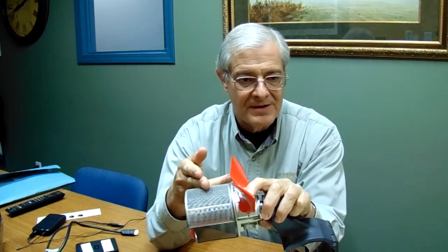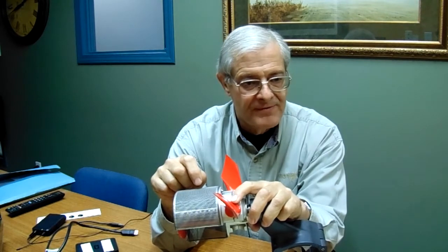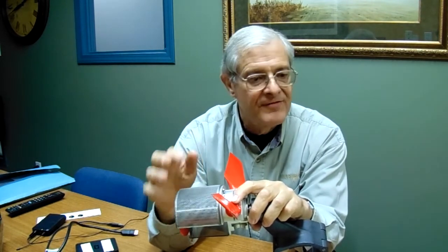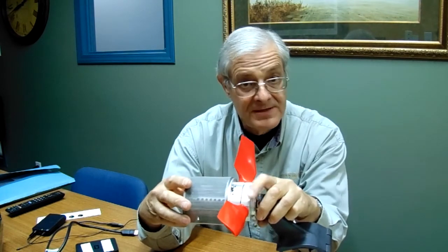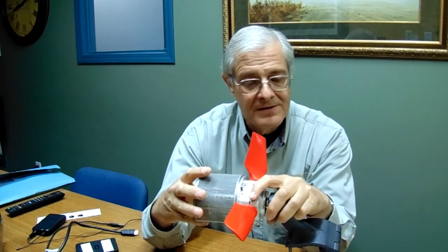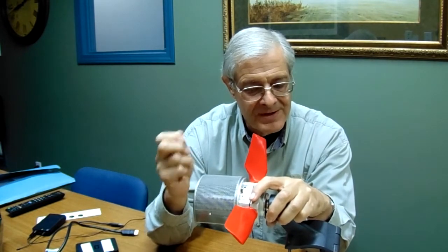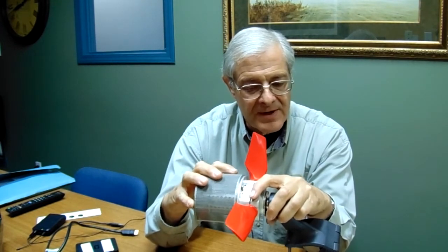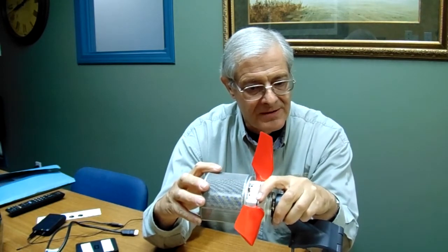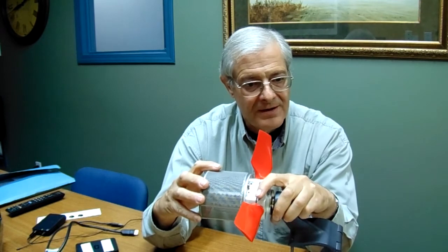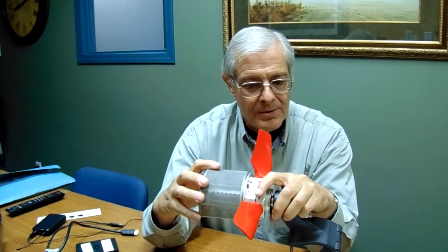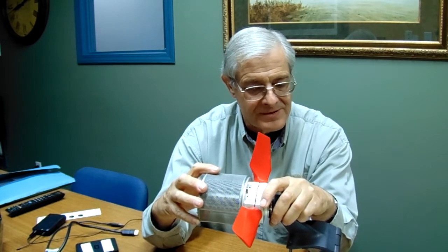On the rotary atomizer, much the same thing's happening. On the surface of the woven cage, you have the crossings of the wires. So the liquid will stream off the crossing of the wire, form a ligament that will then break off as a droplet. But because the atomizer is rotating, you've got the centrifugal force stretching that ligament, and therefore everything happens much more quickly, there's much more energy being put into it, and the droplets that are formed are a lot smaller. So instead of a big drip from a tap, you get a small droplet. But the actual size of the droplet depends upon the rotational speed. So the faster the atomizer is turning, the smaller the spray droplets you produce. Or if you want to produce bigger droplets, you slow down the atomizer.